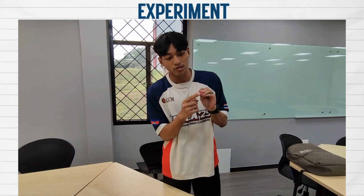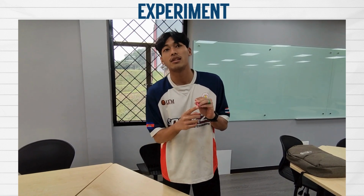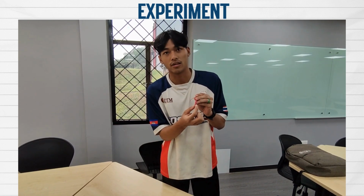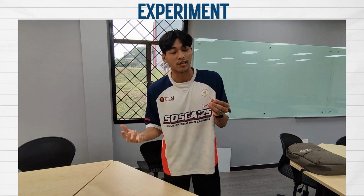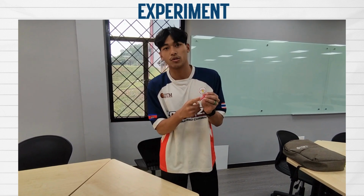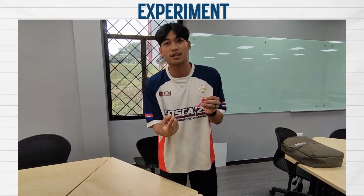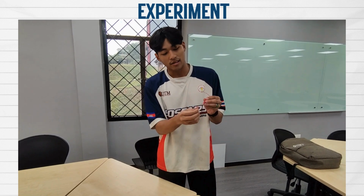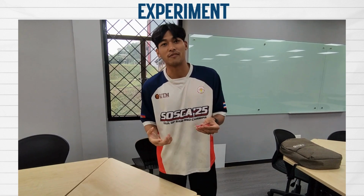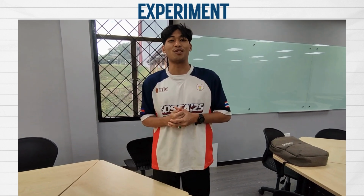And if I were to use a different material, because different metals have different capabilities for concentrating the magnetic field. Normally people will use a laminated iron core, and the wire also plays an important role, and also the number of coils. The higher the number of coils, the stronger it gets; the higher the current, the stronger it gets; and the different material also plays a part in how strong the electromagnetic field is. So that is for our simple experiment. I hope this helps you all.